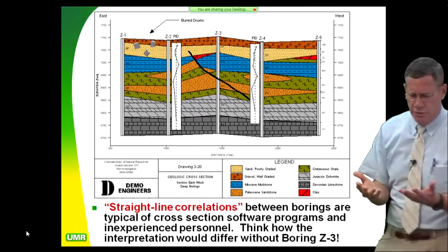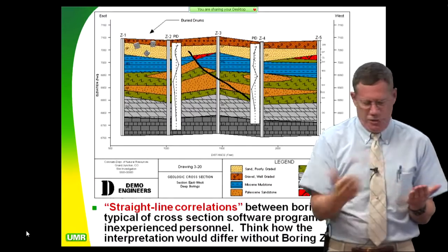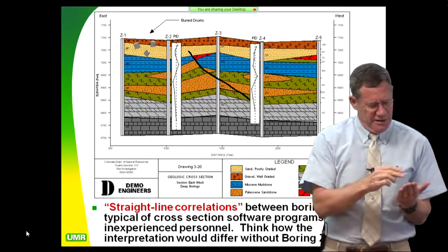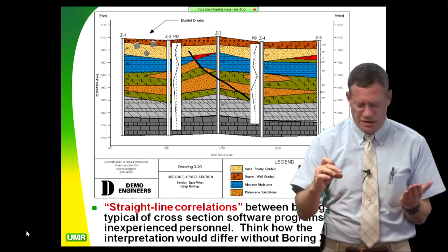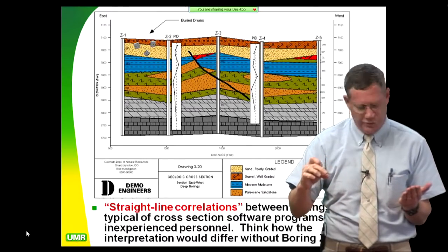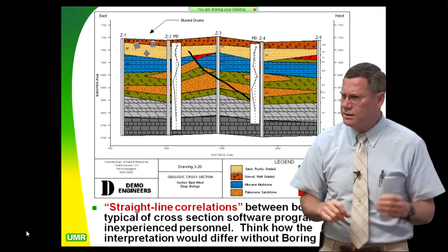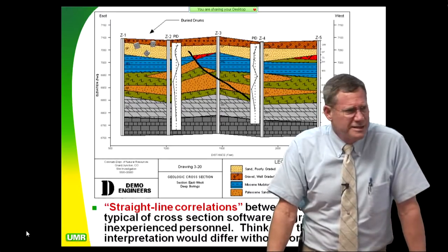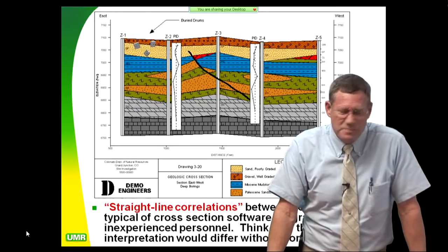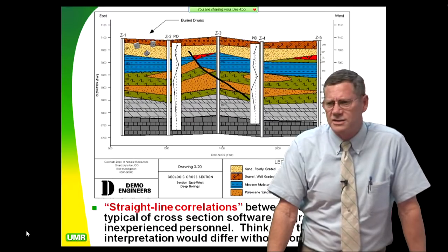So I'm looking at the borings, and I grew up in the business, and wow, these things really correlate well. In fact, this unit had the exact same thickness and the exact same moisture contents at every depth. 17.38% moisture, 17.39, I mean, to the second decimal place. You know what that is? That's BS. That's impossible. You can't get those kind of correlations.